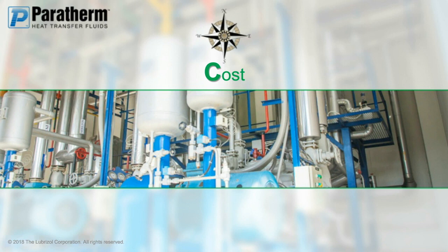You'll be much better off by making an equipment modification to put an inert gas blanket on your expansion reservoir. That completely eliminates the potential for oxidation if it's installed and operated correctly, and will be a much less expensive and much more fail-safe decision to make than choosing to go with an oxidation-resistant product moving forward. And that's a cost factor that you need to put up front over the long term. So that all comes down to considering the bigger picture. You have equipment costs, you have unplanned maintenance, downtime, and safety. These all need to be taken into account.